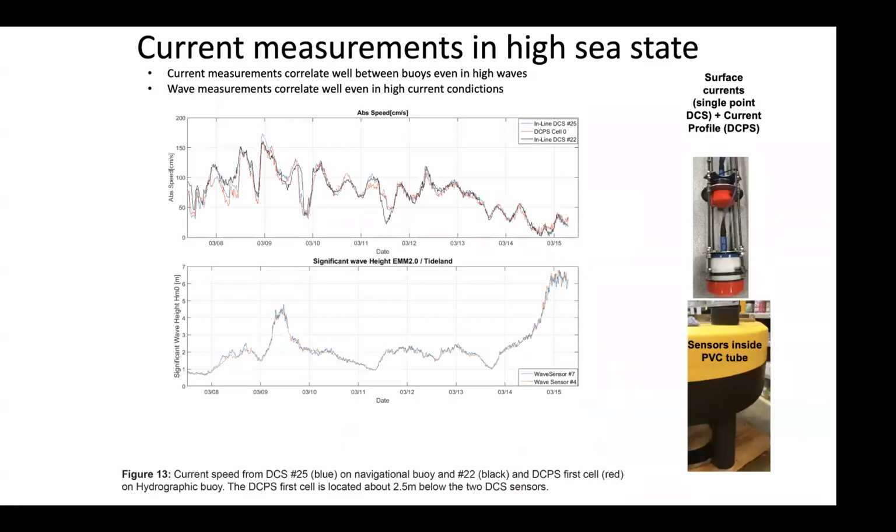And how can you measure currents in really high sea states? Yes, I think from the deployments we have done off the coast of Norway now for 2 years, we can say that this is absolutely no problem if you compensate every single acoustic ping for your movements, and also you compensate for the rotation. And what we have here is an example of that.